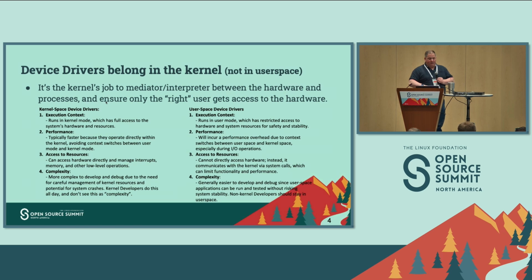And there has always been, for probably the last 10 years, this concept of user space drivers. And user space drivers are great, but they're also terrible. They are great from a developer perspective. You don't have to be a kernel expert to write a user space driver, so you can save yourself some headache. The disadvantage is you don't get to use the kernel infrastructure that is there to make your job as an embedded engineer actually easier and more performant.